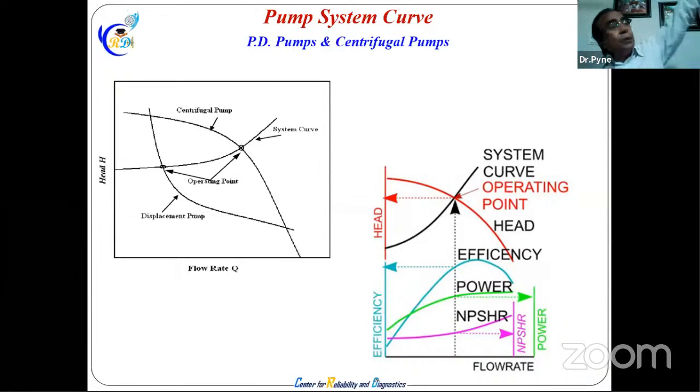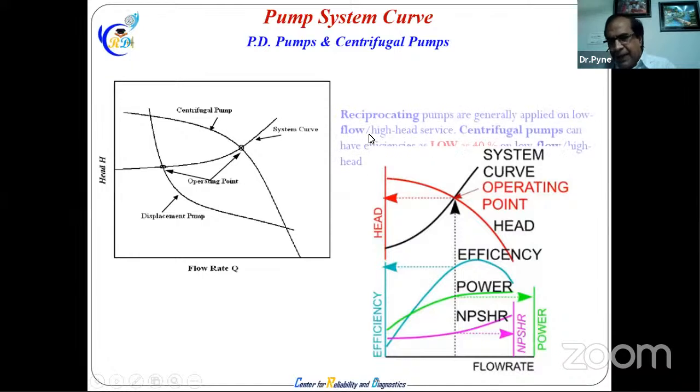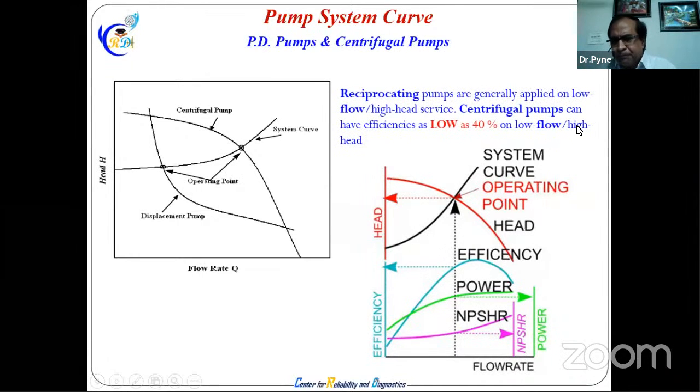If somebody is taking more height, it will not pump more. So HD and FD centrifugal pumps, different pump selections, and head and flow matter. And these pumps have to encounter the system curve. Depending on the system curves, the flow requirement, and the whole head requirement, you can choose which pump to use. Reciprocating pumps are for high head, high pressure, low flow. Low flow but high head, you can see it like that.